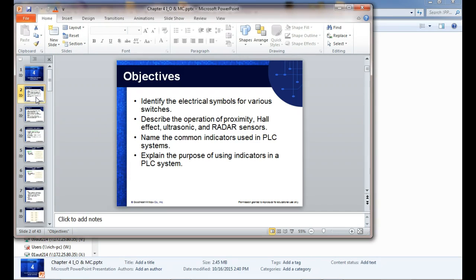And motor controls. So ladder logic, to understand ladder logic, we have these rules, and I'll print those off and give them to you. The book doesn't do a really good job on the rules, especially on the number of output devices that we can have in a rung. So one time it says in the rules that you can only have one output per rung, which is wrong. And then later on it says if you have multiple outputs, you have to put them in what? Parallel. So that's a big problem.